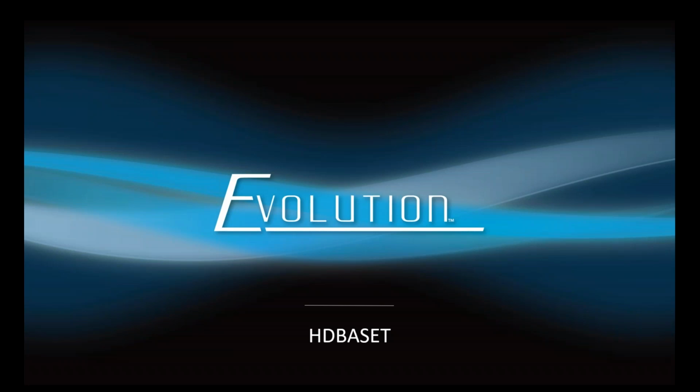All right, let's cover HDBaseT. With HDBaseT, great technology that extends HDMI signals even further. So we talked about the limitation of HDMI, right? Again, 30 feet for 4K, 1080p, limitations about 60 to 70 feet. Now, again, you can go longer with the help of active cables, cables with chipsets, cables with fiber. However, if you still want to use Cat5 or Cat6, you can utilize HDBaseT.